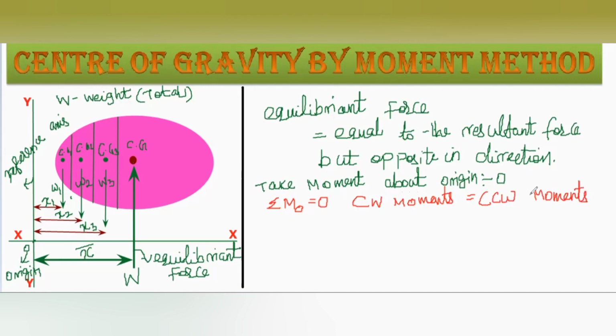Here the clockwise moments will be W1 into X1 plus W2 into X2 plus W3 into X3, that equals the counterclockwise moment made by the total weight and the distance X bar from the reference axis.